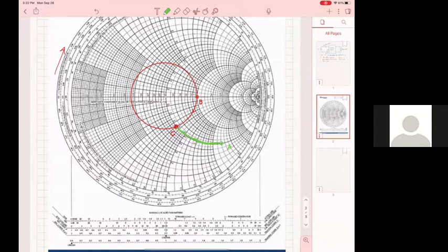And if I move like that, I have to make my negative reactance that corresponds to B more negative, which means I will have to add in series a capacitor. All right, that's how you make something more negative. And when I go from B to A, I change only my reactance.